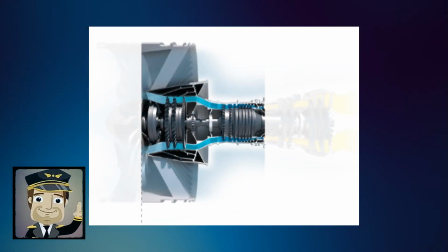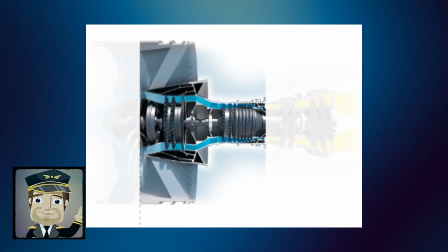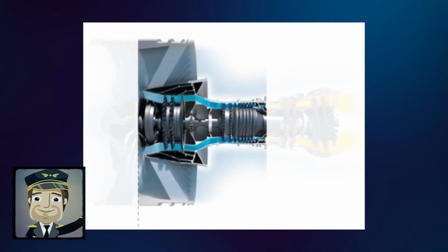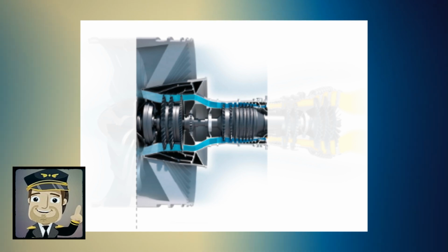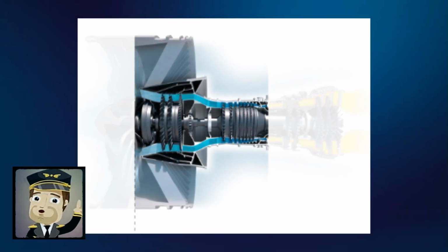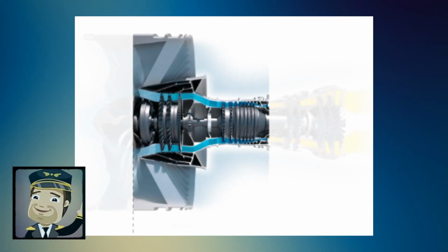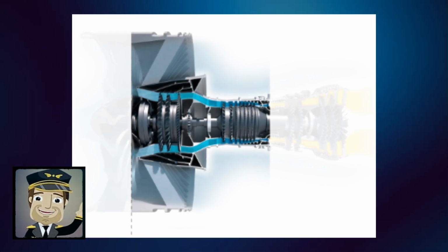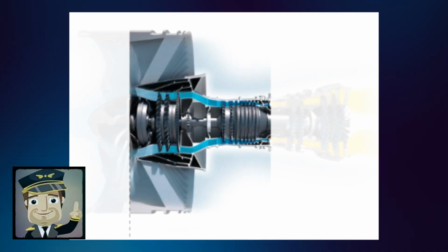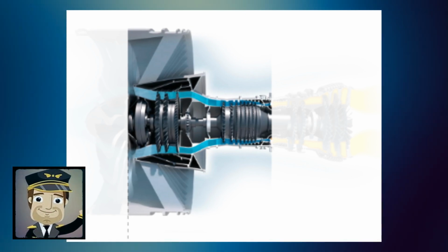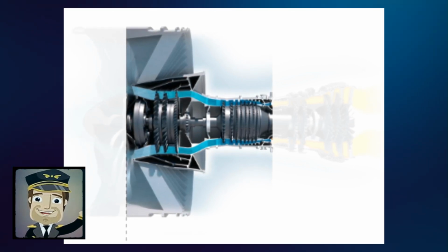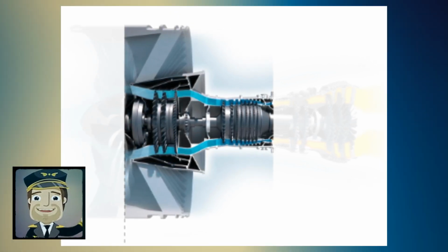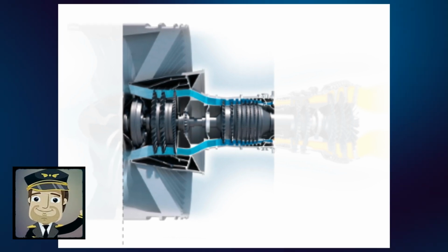in noise emissions. In compression, the portion of ingested air that flows into the engine core is compressed in the low and high-pressure compressors. Also known as a booster, the low-pressure compressor is responsible for pre-compression. The high-pressure compressor handles main compression and offers a high degree of efficiency and low weight thanks to its innovative blisk principle, where the blades and disc are manufactured as a single part.